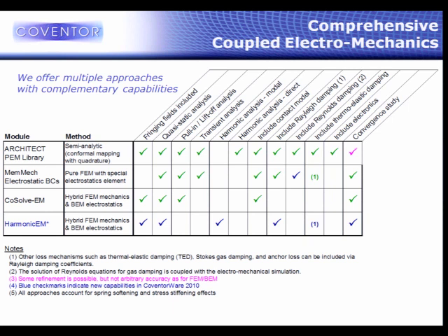And you can see that Architect or MEMS Plus do all of them. The only thing it doesn't do is harmonic analysis using a modal approach. It's using a direct approach, but you can still get at the mode shapes. There's one other thing about the MEMS Plus approach. Because it's based on these analytical or semi-analytical models, you can't really do a convergence study.